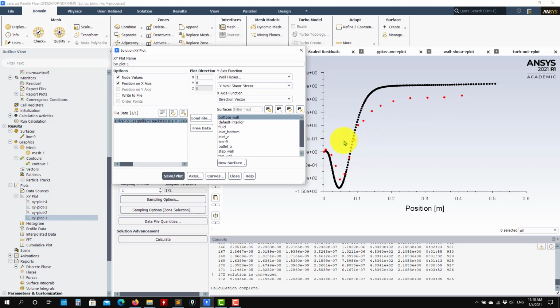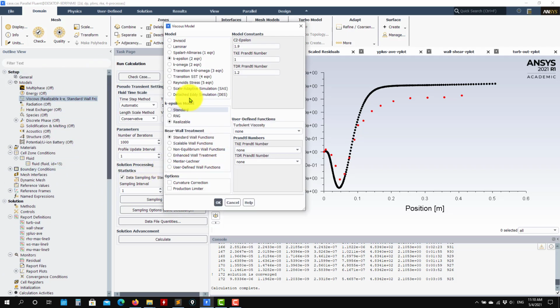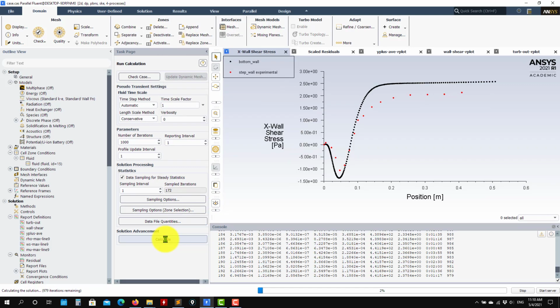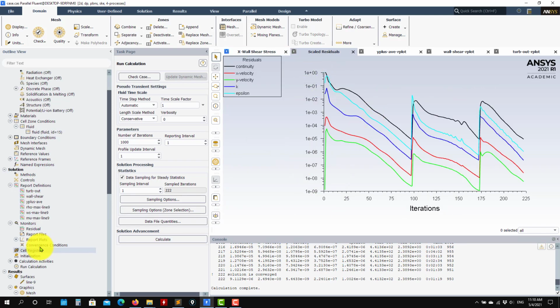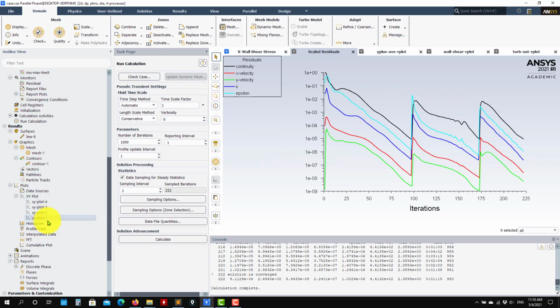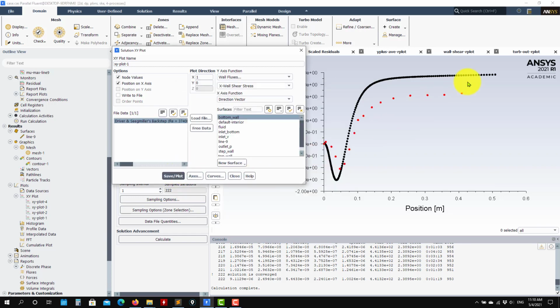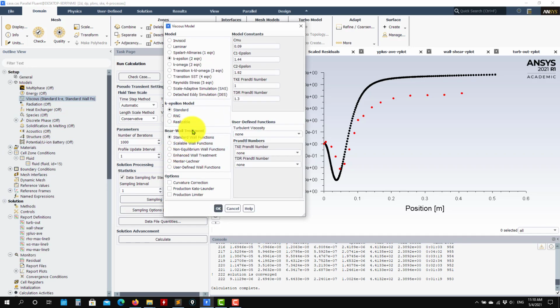Okay, so this is very specific for this kind of model, the standard k-epsilon and realizable and all these models. That is, if you get finer meshes, you are going to get worse results. And as you go to the standard, it will be the same. Okay, the standard is the original formulation. Remember, it's based on wall functions, but then it has been reformulated just also to solve the boundary layer. So I switch to this one, and I expect also to have bad results. Okay, so now as I check here, see that again, these are even worse results. So you can see that different formulations will have improvements, okay, but not necessarily realizable would be the best one for all cases.